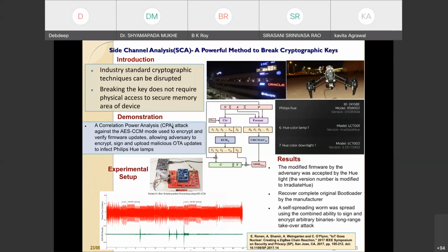But not just anybody can update the firmware, because when the firmware is updated and you want to put it back and re-execute it, there is a security technique called AES-CCM, which is an authenticated encryption. That means encryption is done and authentication is performed using the AES block cipher. There is a secret key involved, a 128-bit secret key. Of course, the attacker cannot guess the 128-bit secret. So the attacker essentially took